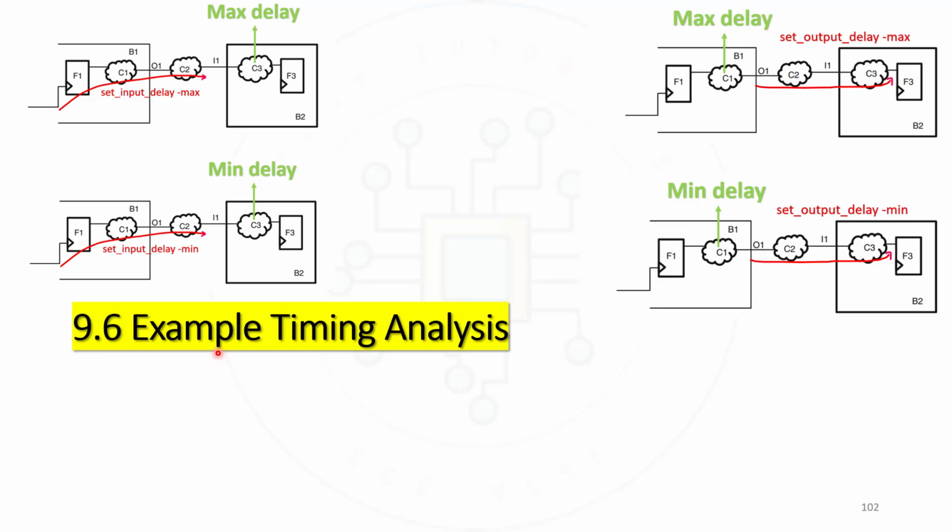Let us try to understand the example of timing analysis. Here we shall try to understand how the timing report will be presented for arrival time and for required time, and how slack will be calculated. And let us try to understand setup and hold as well.